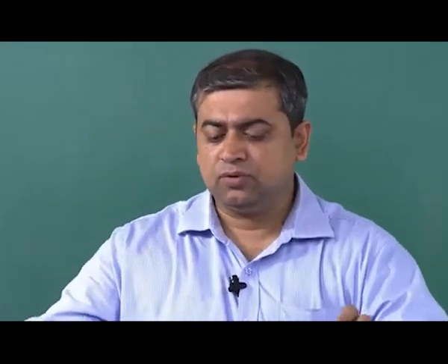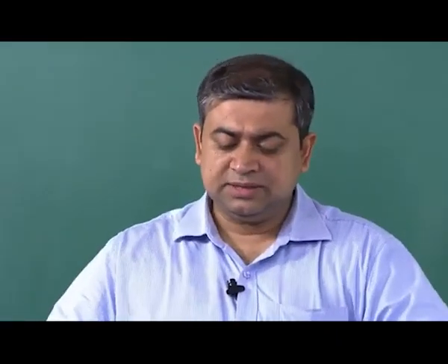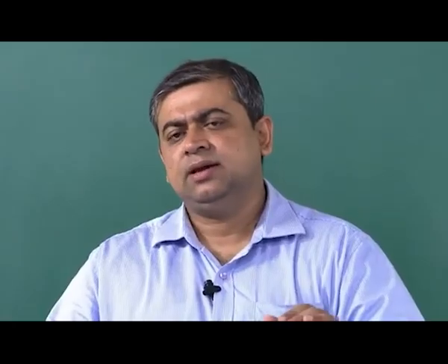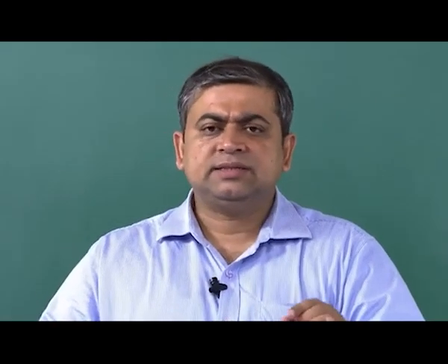important points about e-beam before we stop this lecture is that since the machining by e-beam is achieved without raising the temperature of the surrounding material, there is no effect as such on the work material. So, it is a very high resolution process, as has been illustrated before. The surrounding material really remains unaffected. Because of the extremely high energy density, the work material, even up to the extent of only 25 to 50 microns away from the machining spot, still remains at room temperature. Okay. So, whatever deliverance of heat energy is associated with the e-beam process is really limited to the work area for which it is intended or targeted.